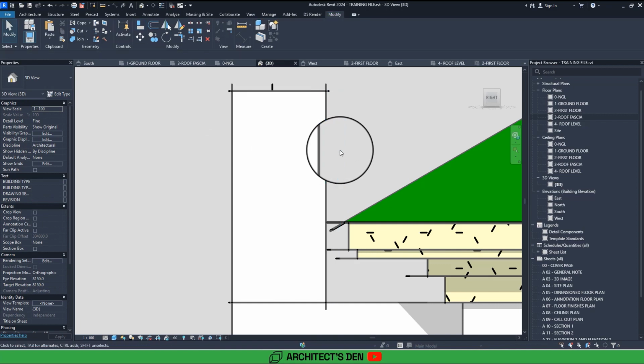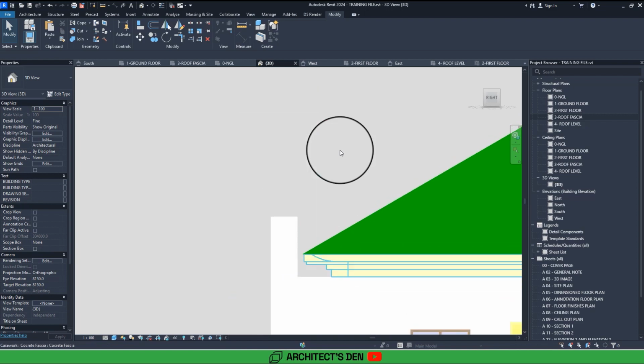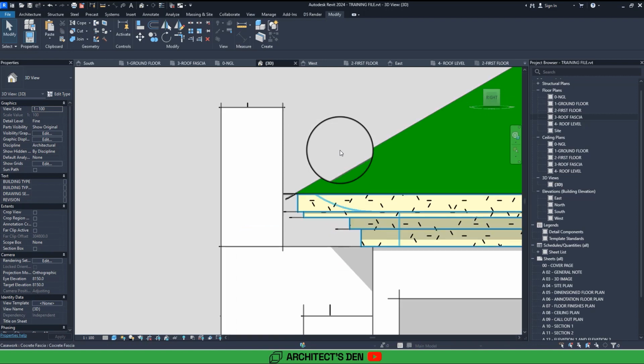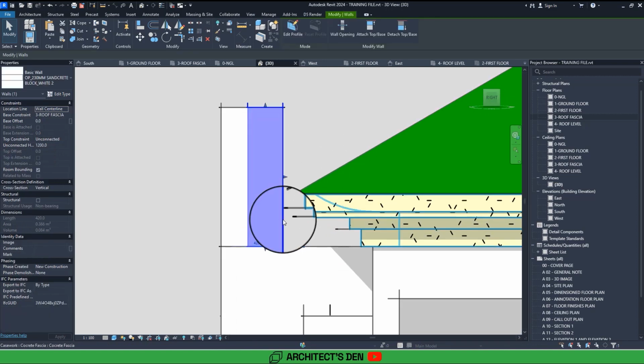So what I've just done now is I'll do this way. We have a slab here. We have a water collector here going into this point, and any water that finds its way anywhere on this slab, you just put a drain to collect it into one of these places. So I'm just trying to reduce all the stress. I might edit this wall in such a way that it goes to this point, but that's all, not above the roof.